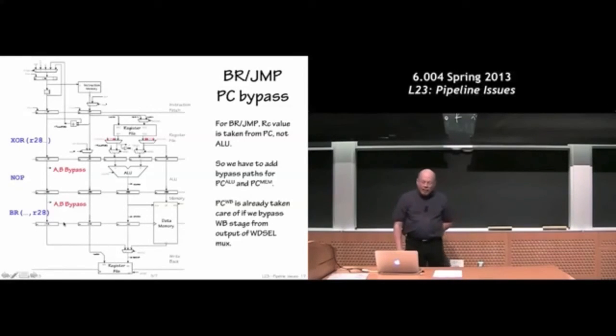So it turns out that our bypass muxes are even piggier than you thought. Not only are they bypassing 32-bit values from this wire or down here, but we also occasionally have to be able to bypass the PC+4 values in the ALU or MEM stages.